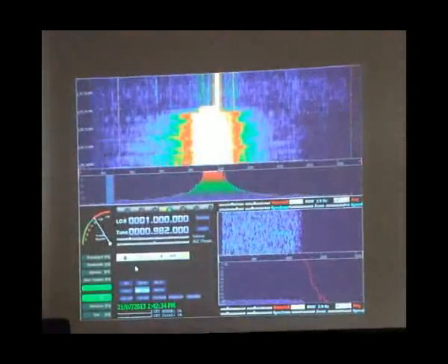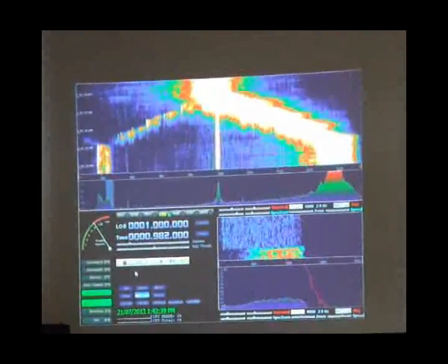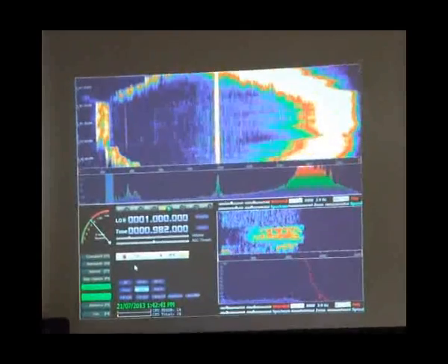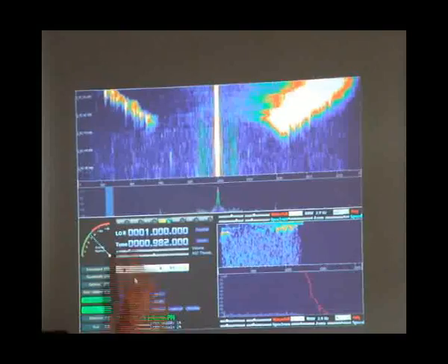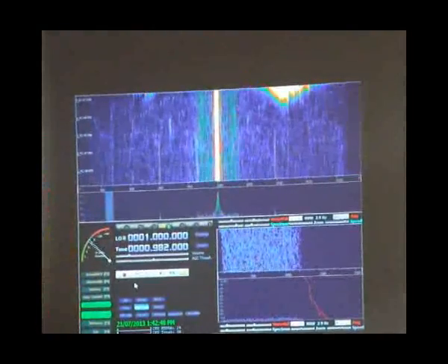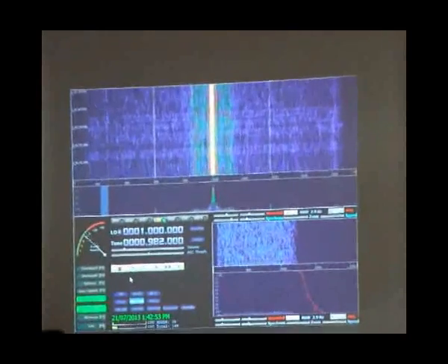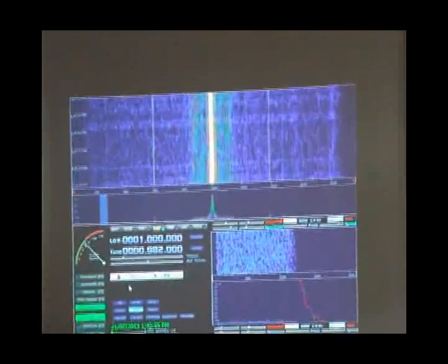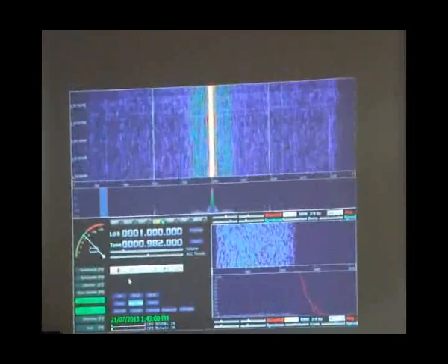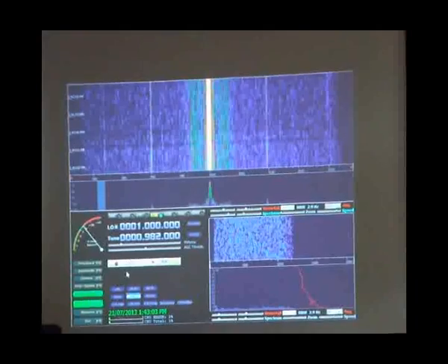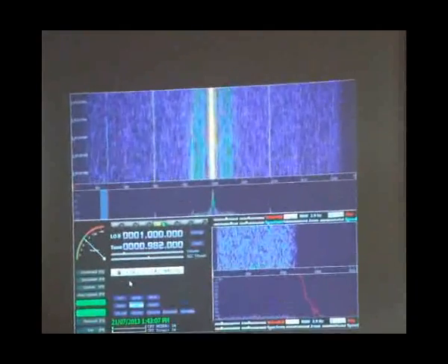Yeah. So if I'm tuned off, okay, there's this signal there. There's that central spike, and all I do is tune on, following it, oh, it's gone. Oh, well, it was there, but anyway. So it's very, very easy. It's quite intuitive once you get the hang of it. I find I use the spectrum scope all the time now for HF work. I don't think I could go back. I have gone back, but I find it difficult.